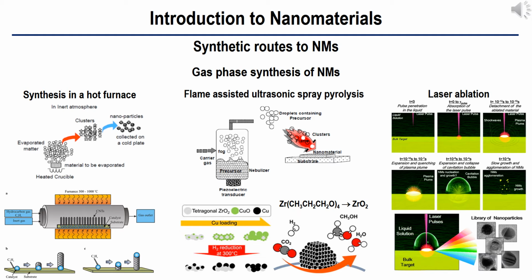In conventional chemical vapor deposition, abbreviated as CVD synthesis, gaseous products either are allowed to react homogeneously or heterogeneously depending on a particular application. 1. In homogeneous CVD, particles form in the gas phase and diffuse towards a cold surface due to thermophoretic forces, and can either be scraped off from the cold surface to give nanopowders, or deposited onto a substrate to yield what is called particulate films.